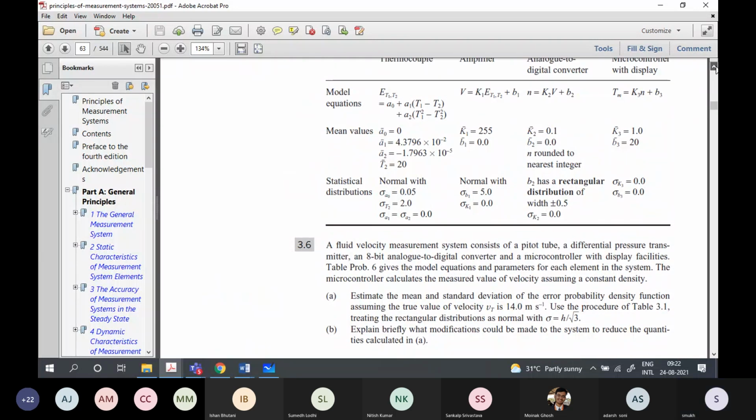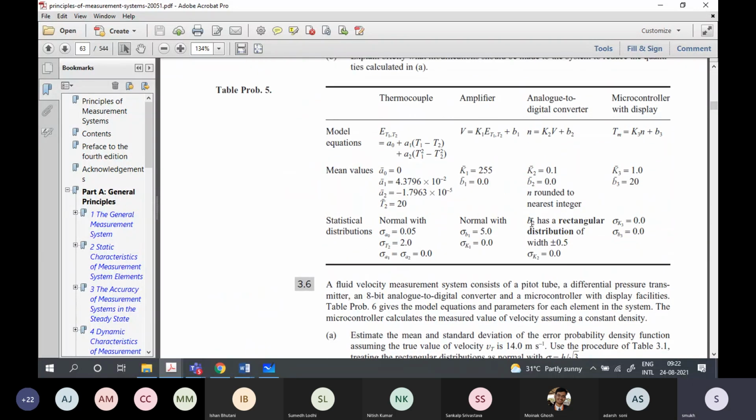Here you see that in some cases he has given a rectangular distribution, but is not looking for worst case values. See, we just saw that if you are given a Gaussian and if you are asked to get sigma, then you will get from sigma the Gaussian and you can do RMS and all that. If you are given a Gaussian distribution and asked for worst case values, then you need a confidence value, and with 99% confidence, if you want, then plus minus 3 sigma will do.